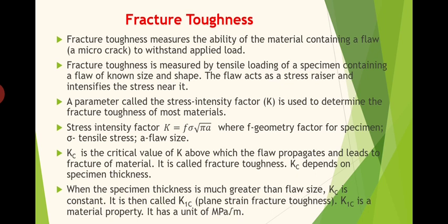So the ability of the material, if we calculate based on the applied stress, will be much less compared to the actual ability. So that fracture toughness is calculated with that high stress concentration. So fracture toughness measures the ability of a material containing a flaw to withstand applied load. Because of that stress concentration, the material will fail before the theoretically calculated maximum stress.